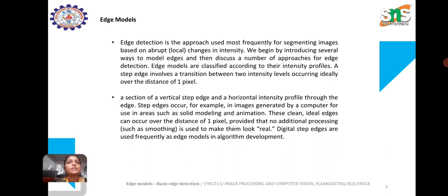And the next one is line detection. Line detection identifies straight lines in images, which can represent edges, objects, or structural elements in the scene. The lines can be oriented in different directions, that is horizontal, vertical, or diagonal, and special masks or filters are applied to detect lines in a particular orientation. For line detection, masks are used to detect different orientations of lines. These masks compute the intensity difference in a specific direction.